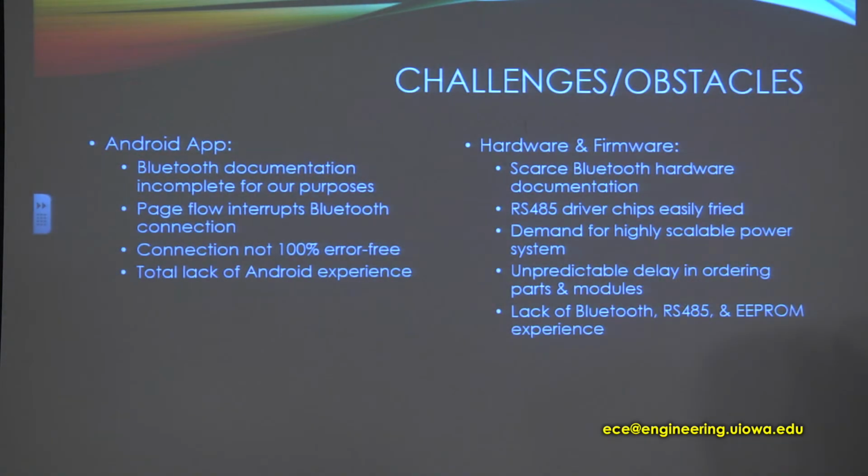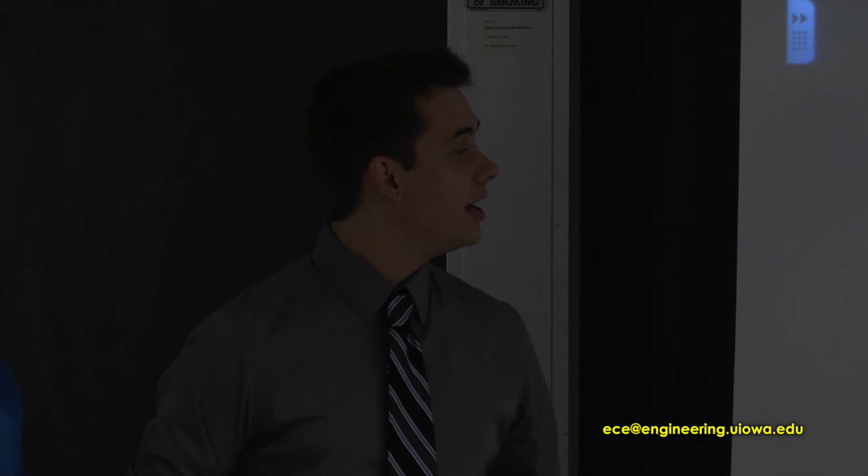The next biggest challenge was that the RS-485 driver chips we used were a lot more delicate than we thought. We started with 25, and I'm pretty sure we have 8 now, because every time we put them onto a breadboard or connected them to our own power supply circuit, they would fry and never work ever again.